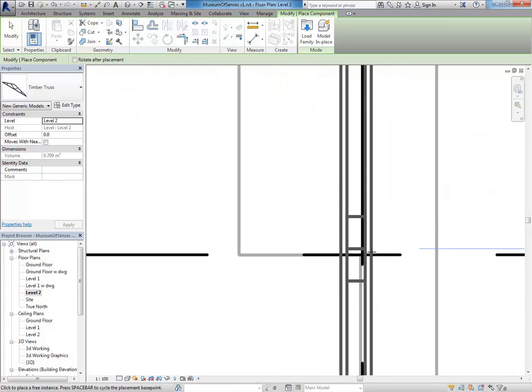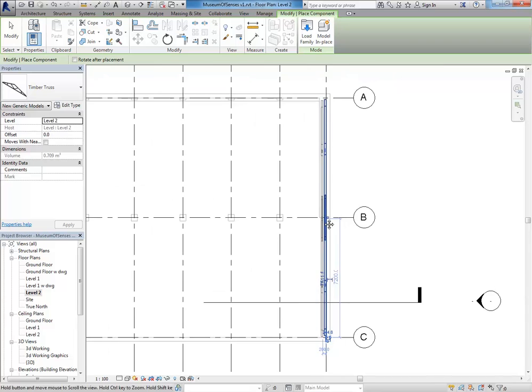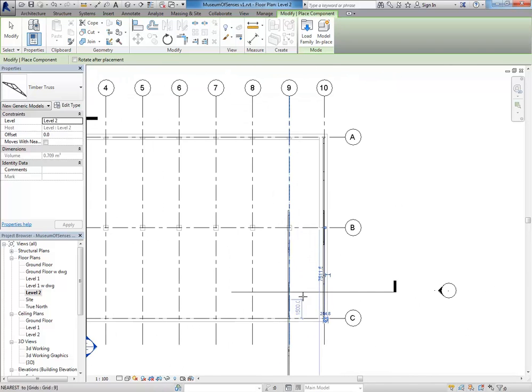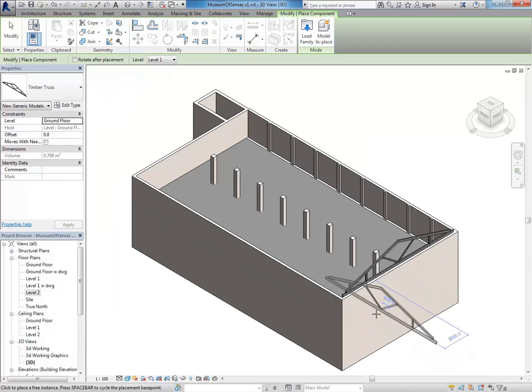And so I'll line that up with the inside of the wall there. And so the front truss is going to be a bit funny. They always are, because that goes with the facade wall. So I've just placed that roughly, but then the others should sit on the column grids. I've got to check that, but I'm pretty sure that's the arrangement.